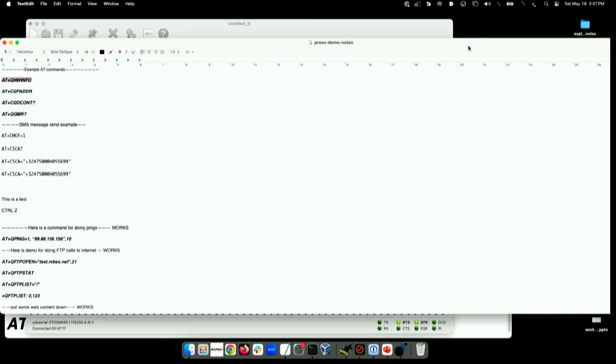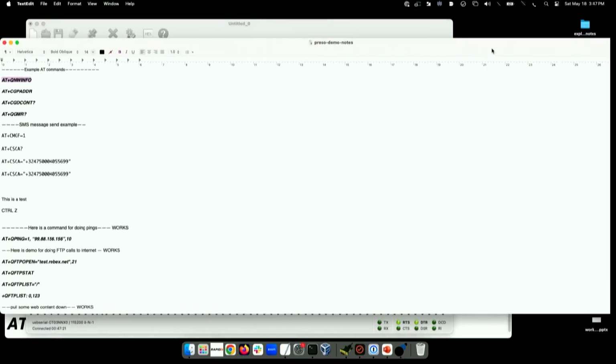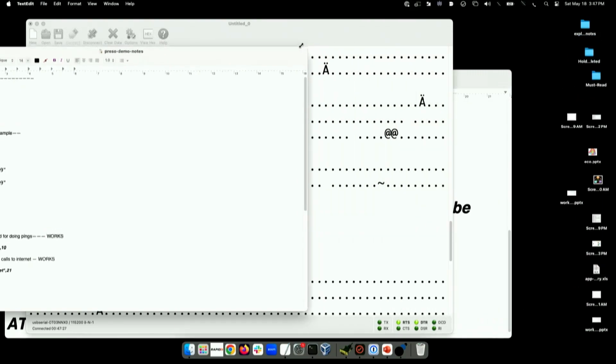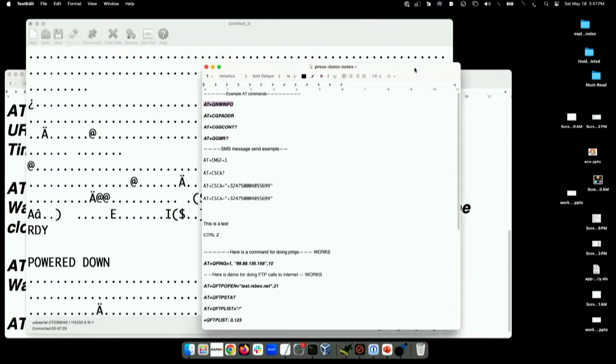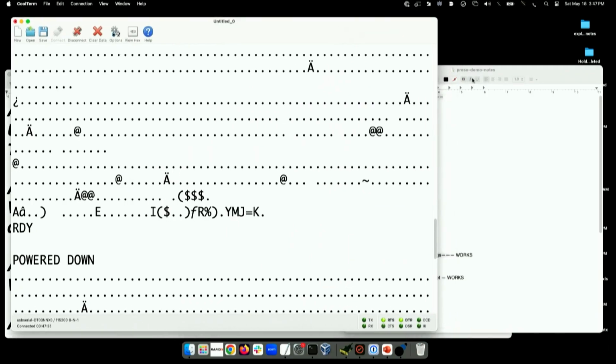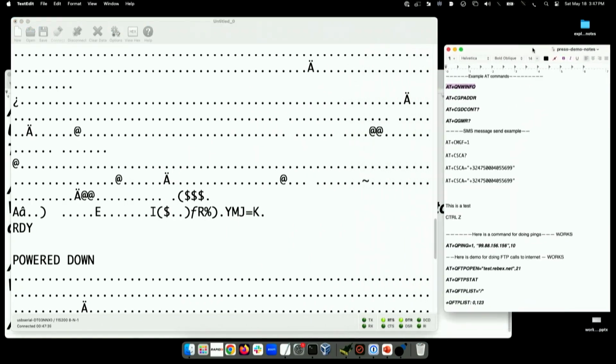Are these commands going into the UART? Yes, they are. These commands are going into the UART. We're able to attach to the UART. Let me shrink this thing down because I'm not typing these commands. What speeds are typical for the UART? I've seen 9600 actually used. Remember, a lot of these devices that just use the UART aren't moving massive amounts of data. It's just telemetry data, so they'll do it low. But almost always 115200.